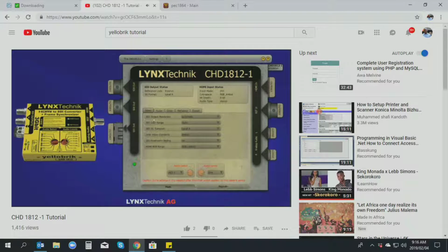So again, these are all the video commands that are available: output resolution, color range, between auto, limited or full color range, whether you want to do level A or level B dual link in terms of the 3G output, limit the video standards to full list or limited list. Quickly, that one means that HDMI can obviously support a whole plethora of different resolutions. That's the full list of possible resolutions.